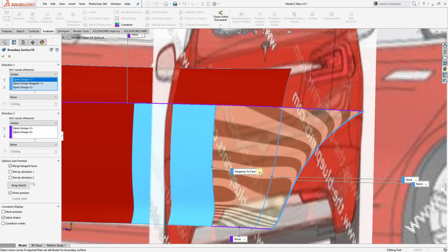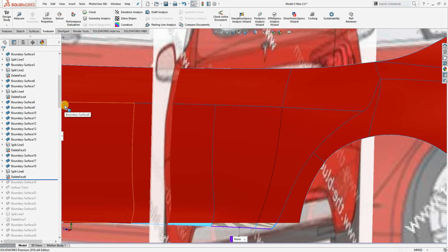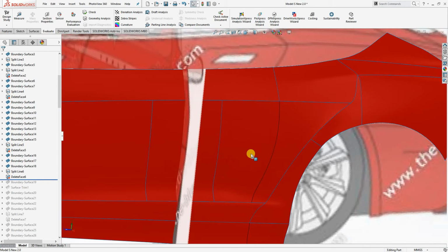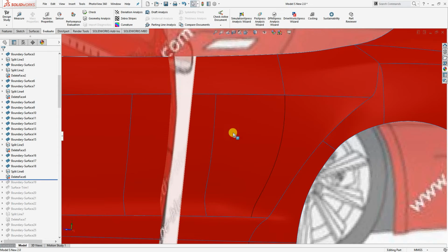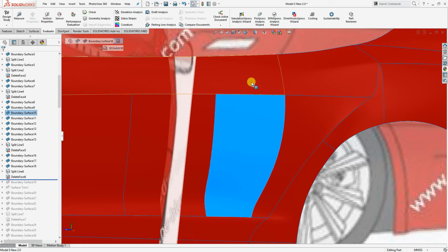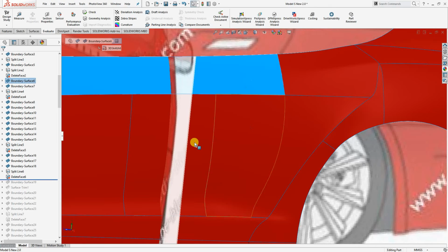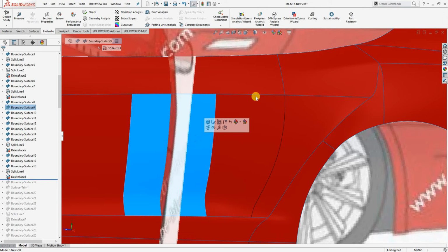So with SolidWorks, it's not always possible to get the curvature to face or the G2 continuity. Sometimes it just simply won't let you do it. There'll be some failure or some underlying problem. Most of the time that's because you've done something wrong, but once a model starts getting complex and you've got a lot of surfaces, for example, if I wanted to make this surface G2 continuity to this and this, SolidWorks might simply not be able to do it.